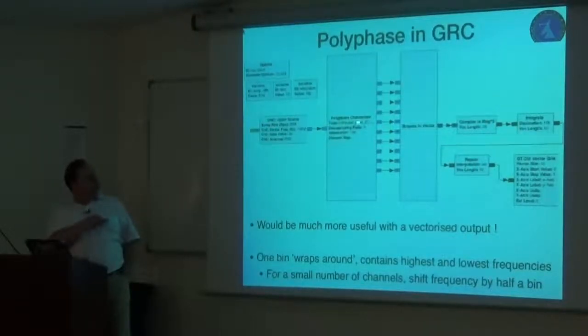You define, as usual, just in a single set of taps, your low-pass filter or your sinc or whatever filter you want to use. And it turns it into all these channels that are properly filtered. And all of these channels will now nicely have only that particular frequency. And the better you make this particular filter, the tighter, again, the filter window is.